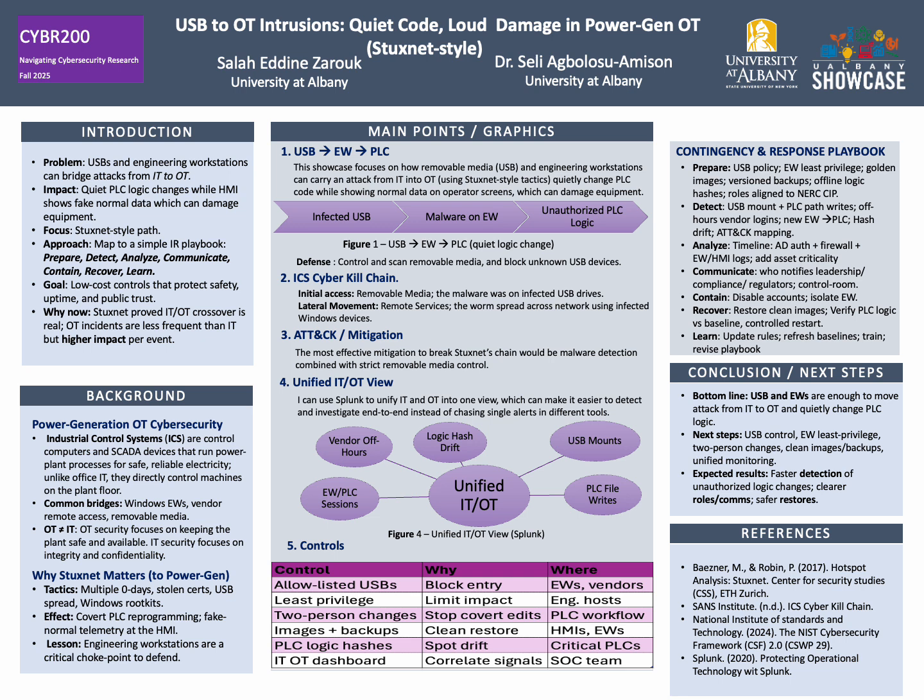Recover: restore from clean images and verify PLC logic against the baseline before restarting. Learn: after the incident, update roles, refresh baselines, train staff, and improve the playbook.